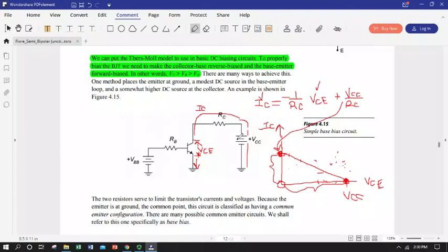So what you choose for supply voltages and resistors flanking this, it's not controlled so much by the base, but our collector and emitter resistors and our supplies will dictate this. And then if we want to operate the transistor somewhere in between, then its beta is playing a role.